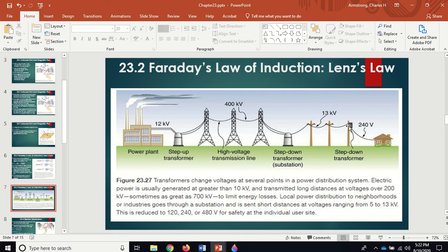Now here you got a transformer that's sitting on a pole. You probably looked up and saw those things and wondered what those were, with those trash cans on the top for the telephone guys to throw their trash away or whatever. No, they're transformers. And that one's going to step down the voltage from 13 kilovolts down to 240 volts. And so that will cause the current to go up, which is what you want it to do, okay? So this is the whole process we go through.